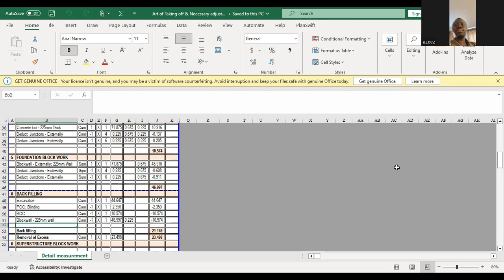There is not enough time for them to collate all the information that will go into those particular activities. So you put a provisional sum, which will be subject to measurement later. So pick any one that you are comfortable with. Then we are going to analyze it together. By analyzing, I mean the quantity that will go into that particular provisional sum and the cost implication for that quantity, and the activities that will build up into that quantity.